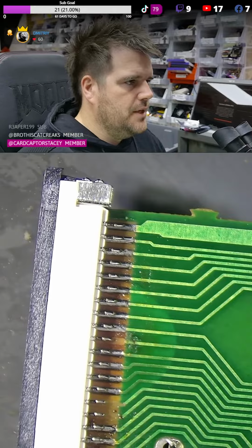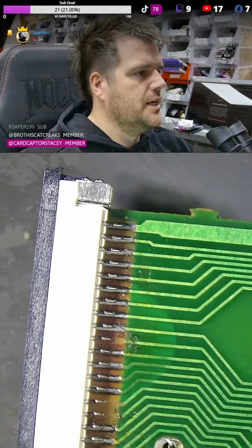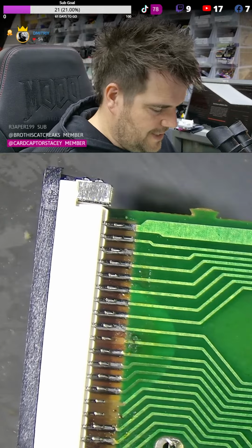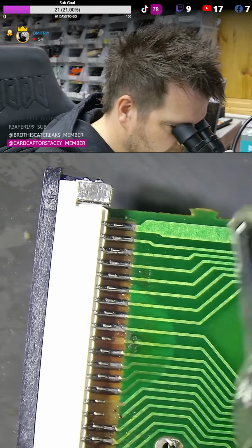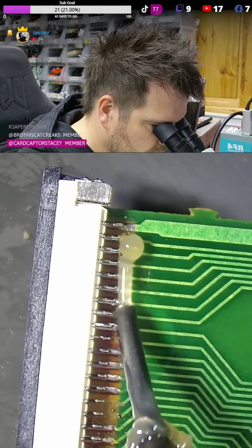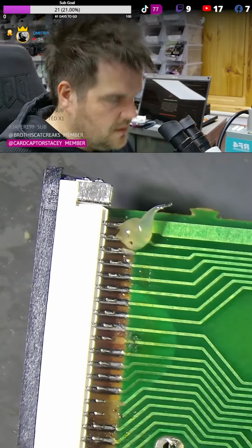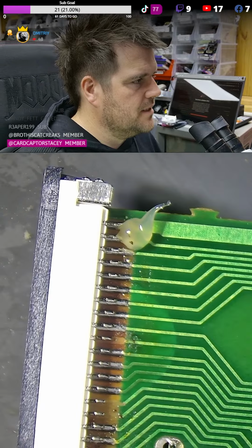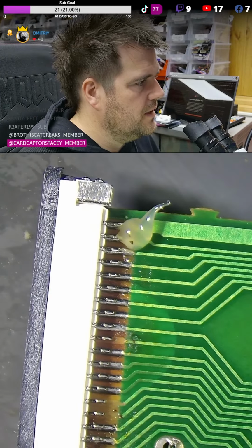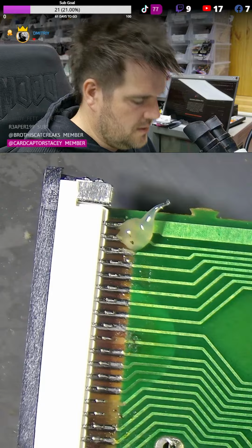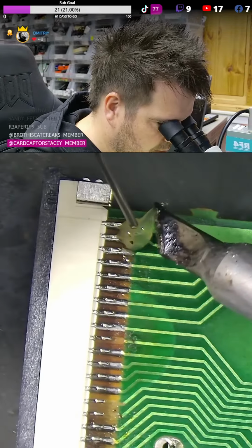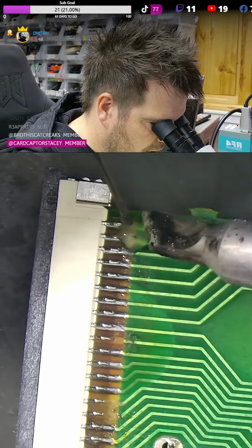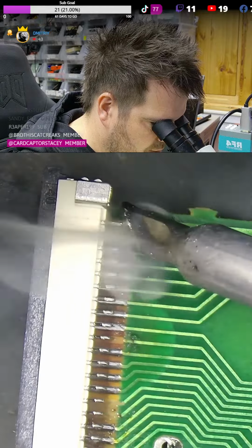And then what we want to do now is, that's already in a quite nice position. I might try and just leave it exactly there without touching it a minute, and get some flux on there, just a little bit. I want to try and tack this into position. Not tried dental floss, no. Like I said, I just use hot air to get most things off, and it's never a problem.